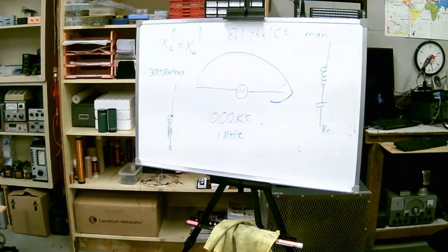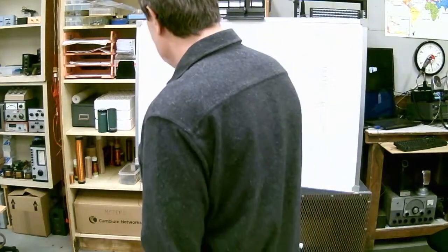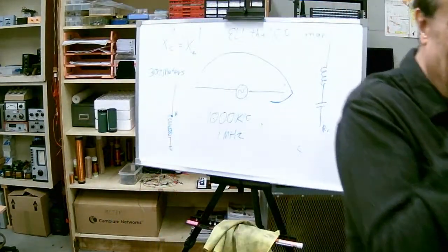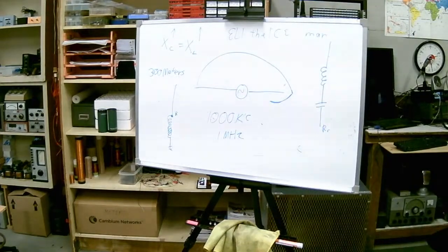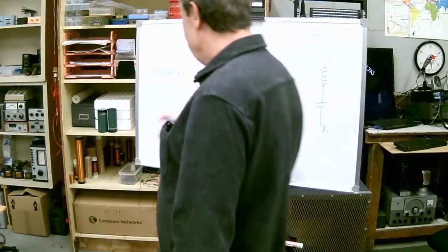That's generally true. For a car radio, the radiation resistance is maybe 1/10 of an ohm. Really? So the resistance goes down with the length of the antenna relative to the wavelength. You get this really teeny tiny radiation resistance.